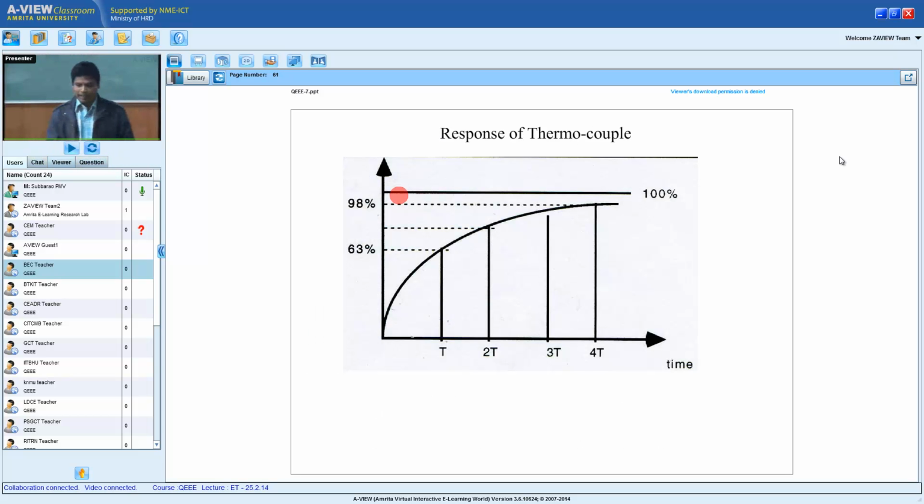You see this one. Let us say I have the system temperature constant. That's why you go to a doctor with a high fever. Your body temperature is almost constant. Now the doctor keeps the thermocouple in your mouth and he has to wait for some time. Why? This thermocouple is in contact with the body for the first time. It cannot immediately show. Slowly the effect of temperature on the instrument is increasing. Suppose the doctor is in a hurry because there are too many patients. If he doesn't wait, what will happen? He is measuring only this much. If he waits some more time, it is closer to the truth. He may think typhoid, it may be malaria, because he doesn't get the correct temperature, or there could be anything else. A high fever can be concluded as a mild fever and there will be a problem.